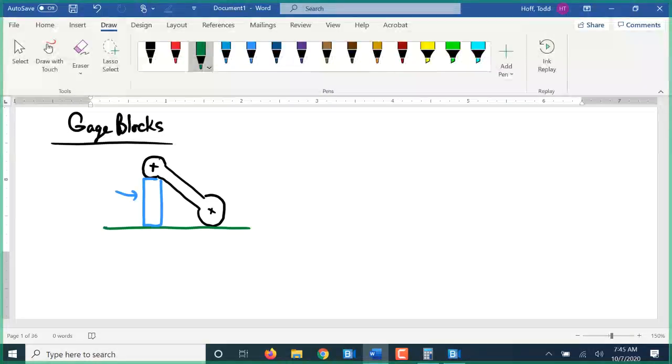For standard gauge blocks, or English gauge blocks as they are sometimes called, we have 3 different series of blocks. There's the 9 block series, that is the tenths, or the 10,000th of an inch series. In this series, because it's a 10,000th of an inch, it is too small to just make by itself. It would be literally hair thin.